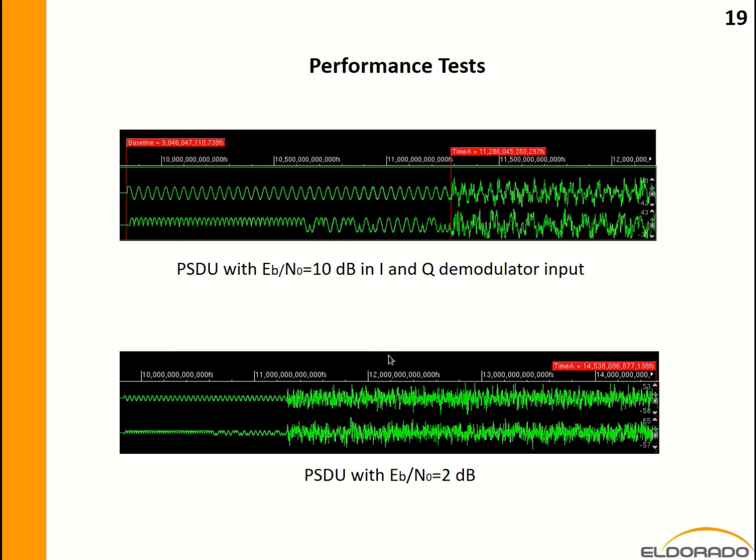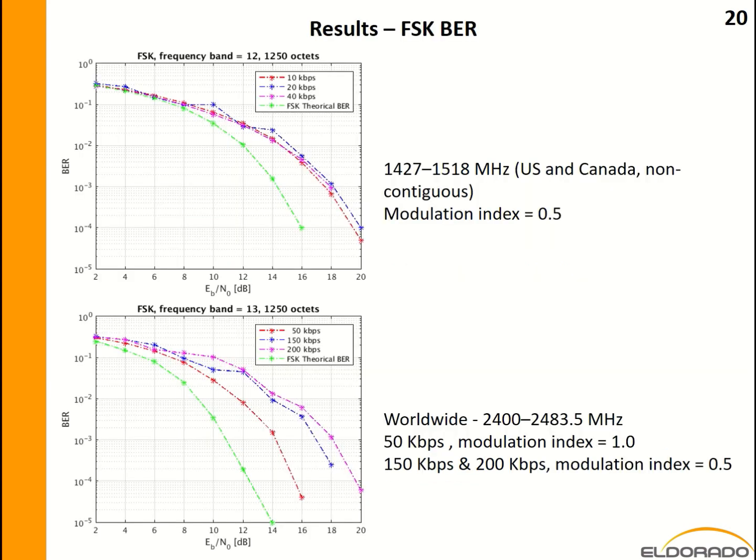Configurations that have low data rates, such as 2.4 or 4.8 kilobits per second, take several hours in simulation to run just one point of BER. To speed up the simulation, it's possible to change the sampling frequency of the system and pass the new value to the configuration object. Then, all the parameters are reconfigured with the new values. Tests that last 10 hours can be executed in less than an hour, just by decreasing the sampling frequency.